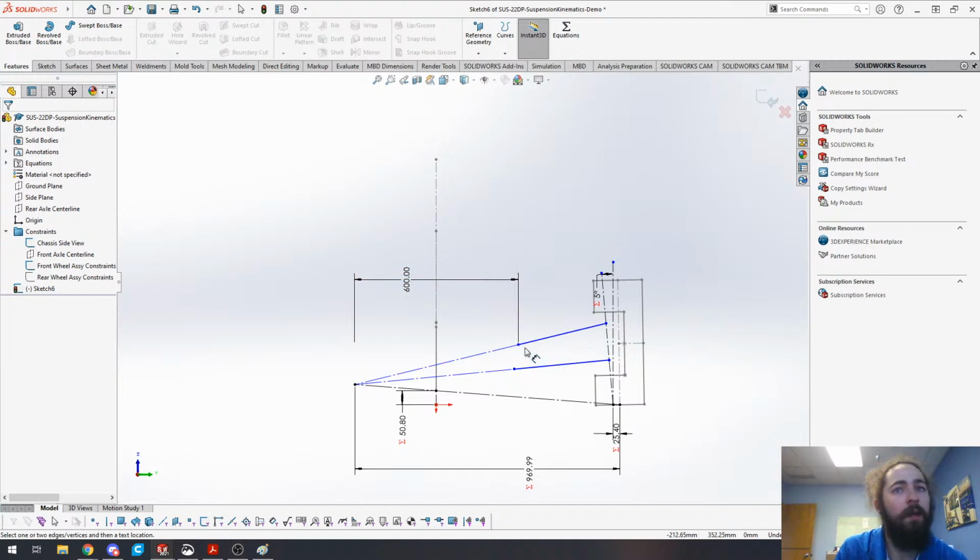But generally speaking, from what I found at least, you want to have these control arms be as long as reasonably possible. That helps out more with transient behavior. Again, we're setting up the suspension based on static constraints at ride height, and we want the suspension behavior to be close to this as we start moving through bump and droop. So having longer control arms means that there's less change in your instant center location and your roll center location, which again we'll demonstrate later.